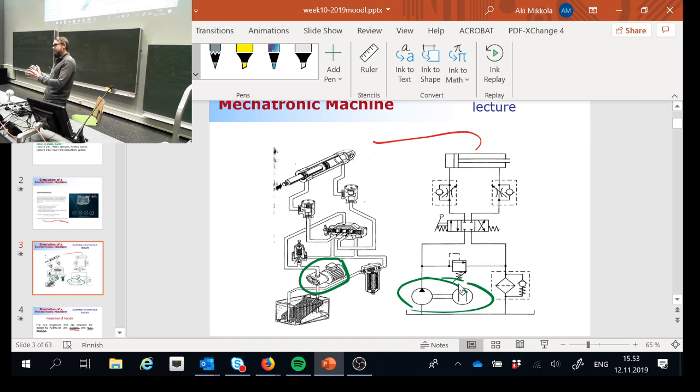Now the new idea is that we produce energy for the system based on the need of the system, and you can make that happen with the help of digital hydraulics. A really clever and very fast system realizes when the energy is needed and gives the command to the pump, and the pump is then either producing power to the system or not. That's digital hydraulics, and it goes all the way to digital pumps. I feel that can introduce quite significant energy savings. So that's it in short. But what was your question?